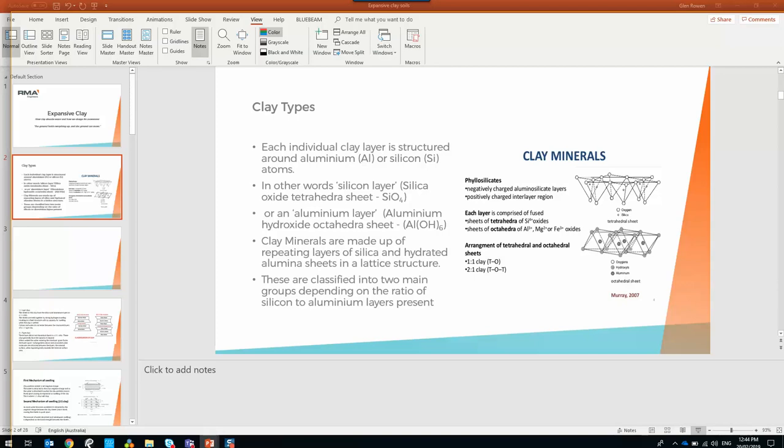So what we do is suspend the perimeter, the theory being that if you go 2.5 metres around the outside, by the time you get in that 2.5 metres, the effects of climatic change on the soil moisture content should be very stable inside the building. So the advantage is it's cost effective for large sheds, but you just have to be a bit careful. If they want to put partitions and offices inside, you'll still get some movement in the centre section. So you just have to find out what the client wants and what they're going to use the shed for.